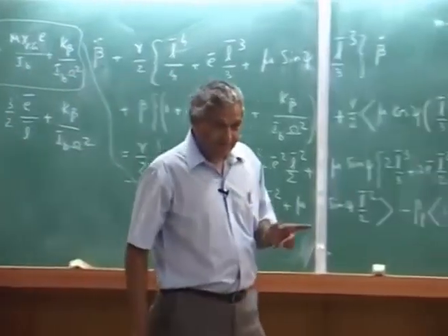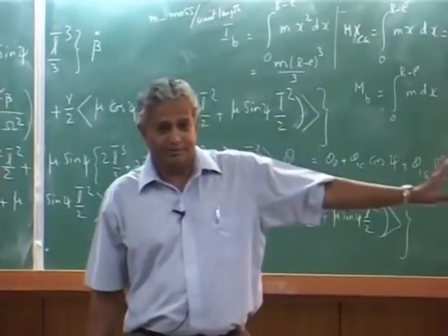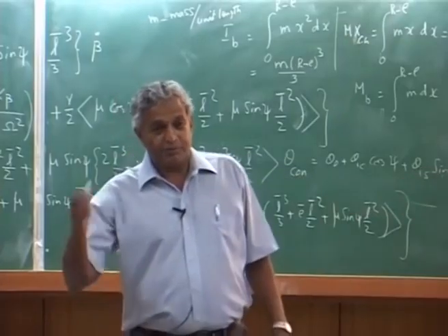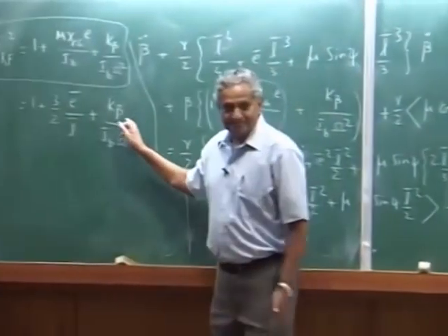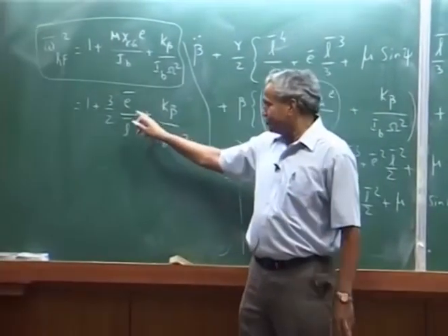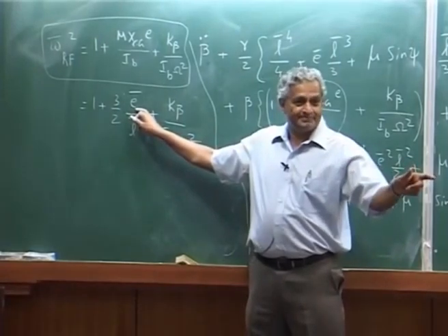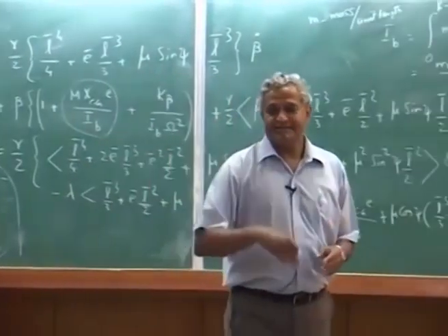That is, my flap frequency will be more than 1 for a rotor blade always. But if I put a spring, I add one more stiffness term. So, you just see the root hinge offset gives a stiffness basically. Your flap frequency is more than 1.